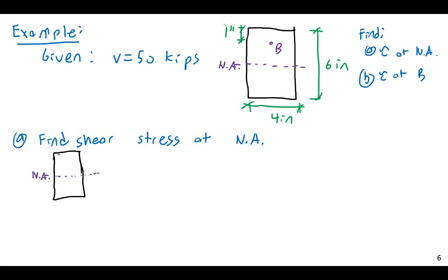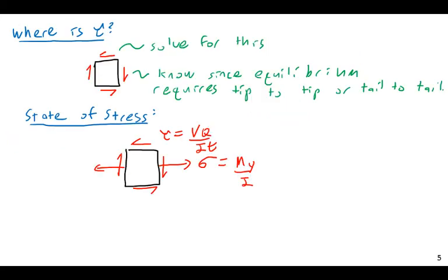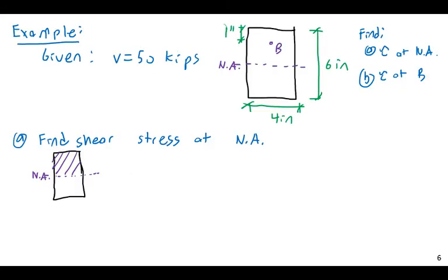The outward first moment of area is going to be based upon this area. The reason for that fundamentally is that when you have a vertical load applied downward, the area above it relates to how much area you have above or below.